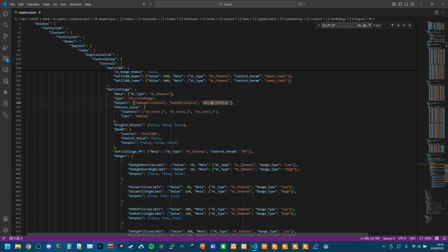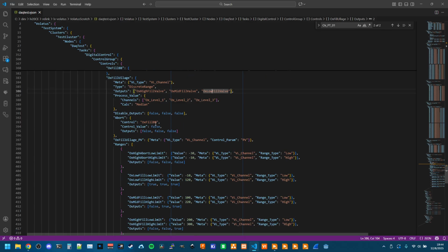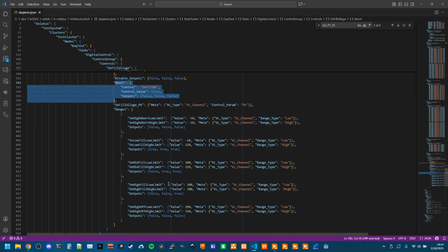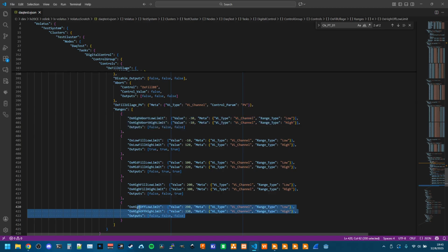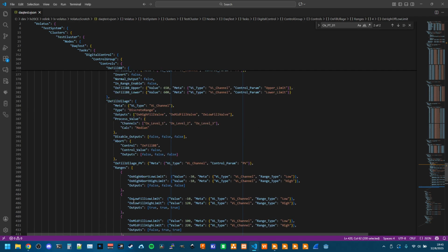And then we've got the abort configuration. I talked about that a little bit. We're going to turn the bang bang off. If abort is configured, you could omit this section completely, and it just wouldn't automatically do anything. It would just stick with whatever either the first lowest range is or the highest range, depending on if it goes past one of the ends.